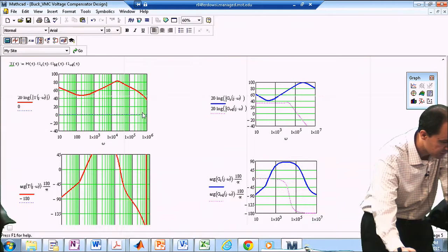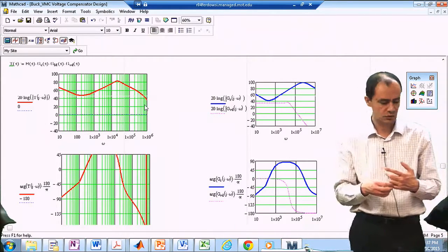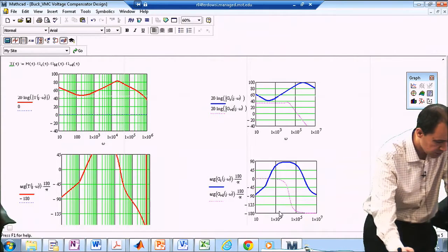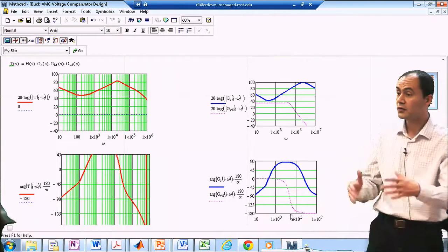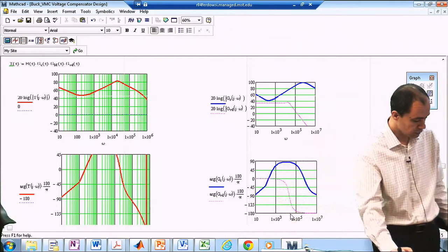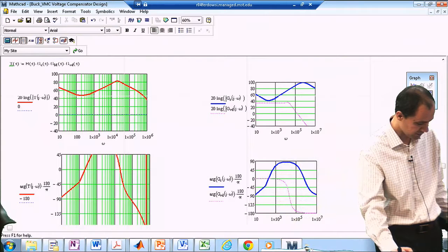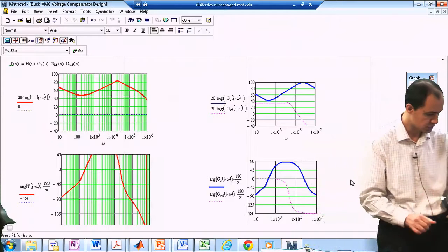And so technically, if you run this, you're going to see not a reasonable output voltage. In terms of phase boost, you can see that because zeros and poles are very far away from each other, because I shifted my zeros to the left, I almost get 270 degrees of phase boost over here. And it's a lot of phase boost, but then you are not attenuating your switching frequency.